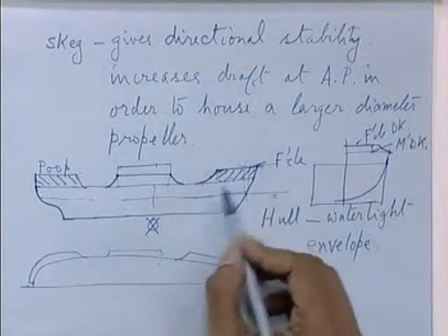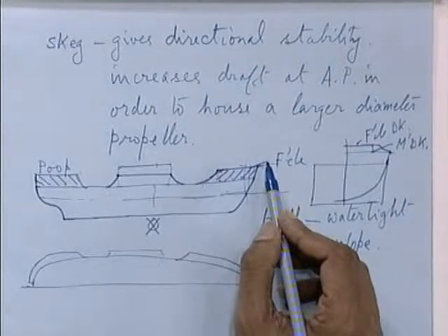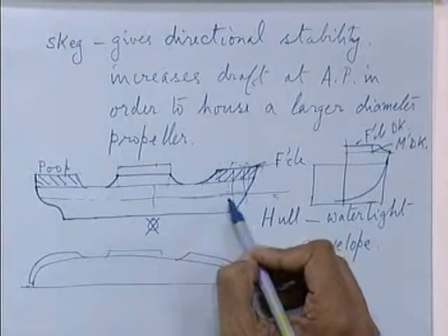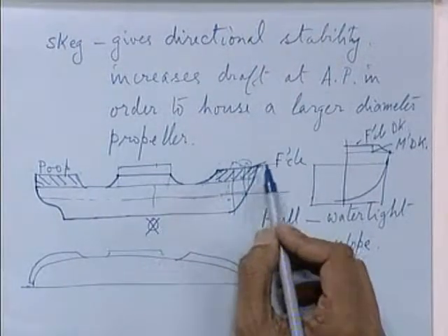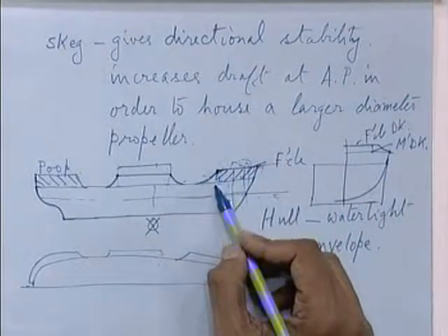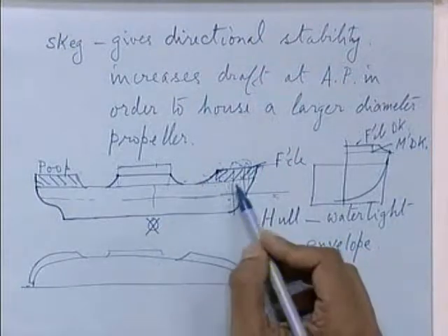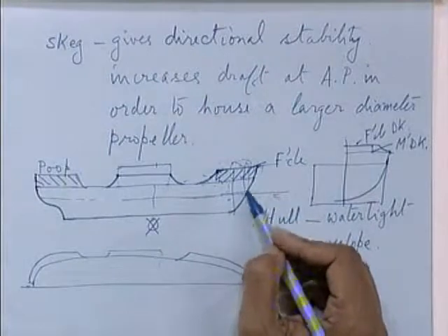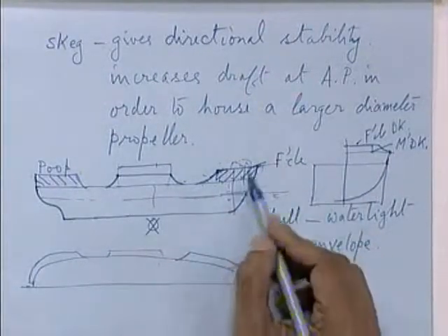Or you can use it for storage of ropes, lanterns. All these are located at the forecastle, and other deck machinery, that is deck items, will be stored. Of course, your windlass will come on top of the forecastle, and here you may have a chain locker that of course will be there, but still other items that are used on the deck, they are normally stored in the forecastle.